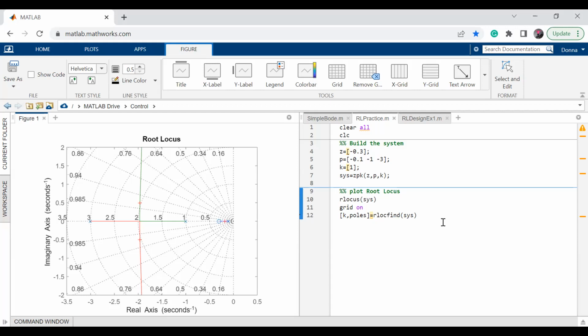Now, what is a pole in a physical sense? Say I have a DC motor and I want to get a certain velocity out of it, and I want to design a control that places a pole. In a physical sense, what is that pole? Because a pole doesn't have a physical meaning. What are you trying to do by adding that pole to your system? You should have been asking me this question three lectures ago, but I'm asking for you.